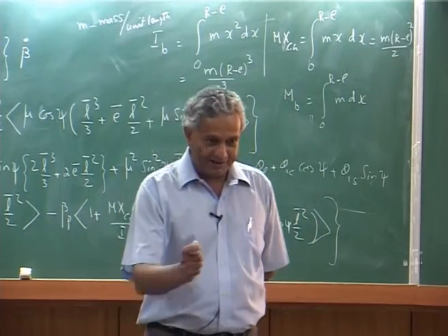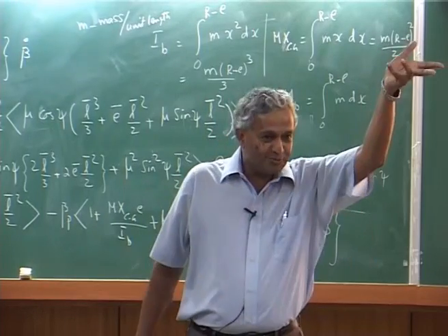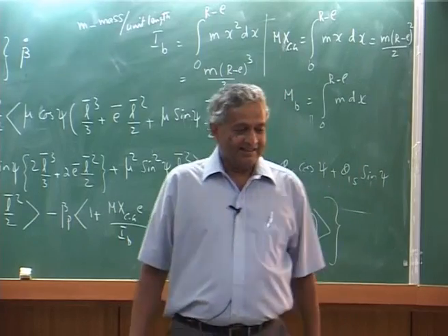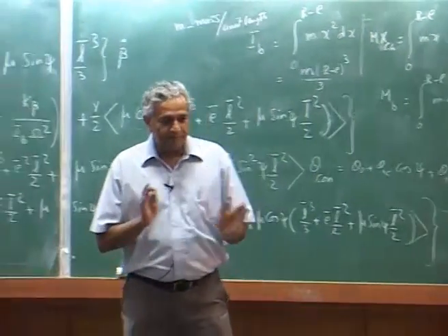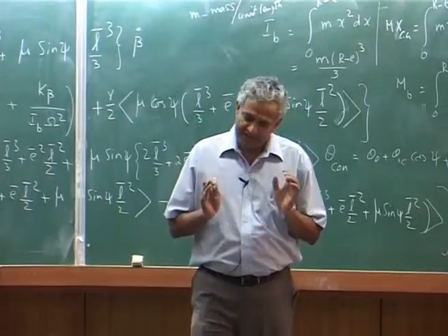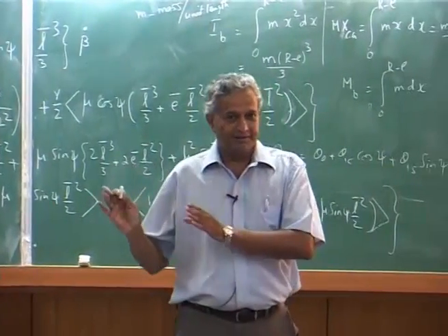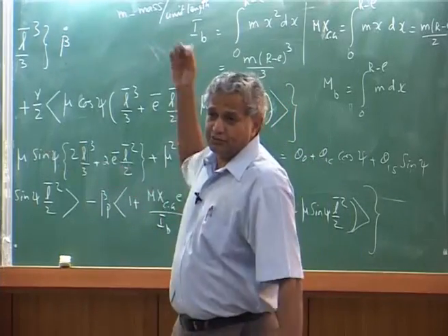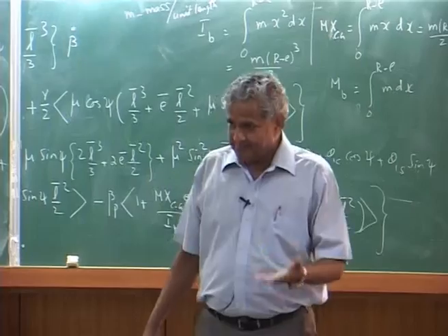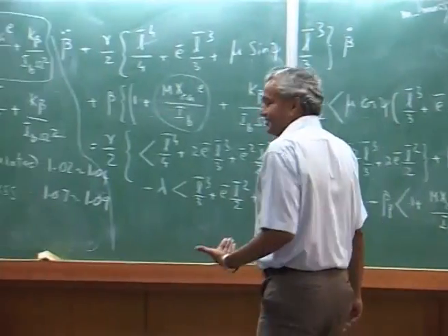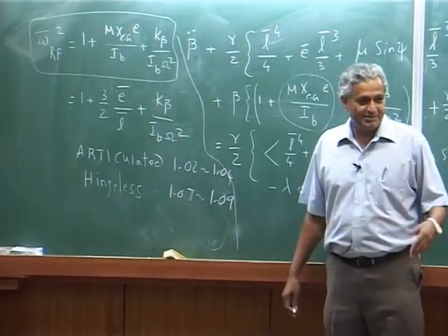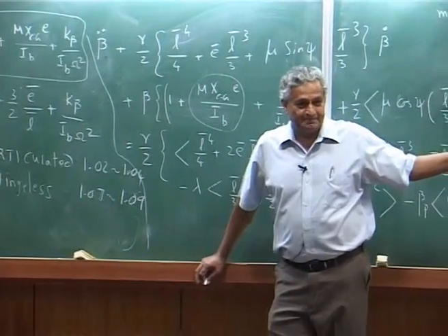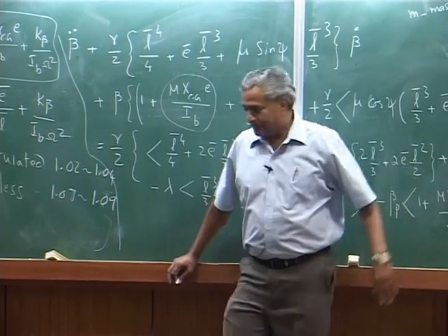Higher control moment means that for a unit stick motion, the pilot gets a large moment; he generates more moment. So that is why the flap frequency is very important in actual helicopter design, but you can't have anything you feel like, because finally the pilot's opinion matters. If you feel it is too sensitive, then you have to go back and redo the entire design. But this is the range.